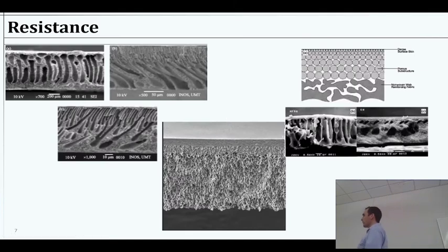So talking about that membrane resistance, here's kind of a physical picture of what that means. These are electron micrographs, basically fancy microscopes that let us see what's happening at a very small level. You can see this little scale bar here is 50 micrometers, for example. Most of our membranes are structured in a manner similar to this, where we have these larger pores that you see here. Water should be able to relatively freely flow through those, and if this scale bar is 50 micrometers, those pores are tens of micrometers in diameter.